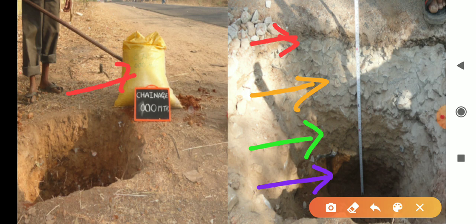The soil within the top 1 meter we will not use for any test. We dig after 1 meter, collect that soil in gunny bags and bring it to the lab, because the top soil contains debris from weathering action, and we don't consider that debris.